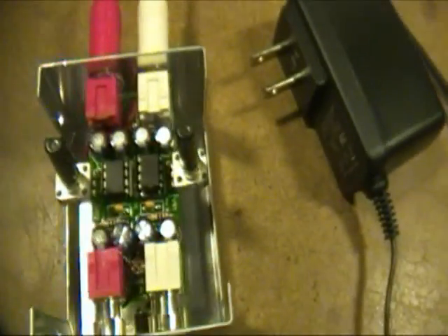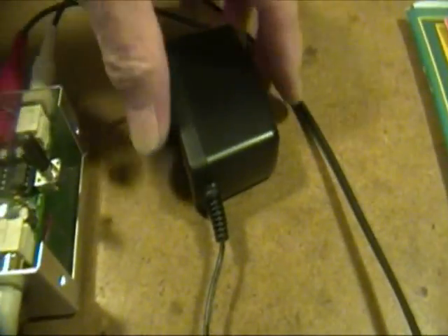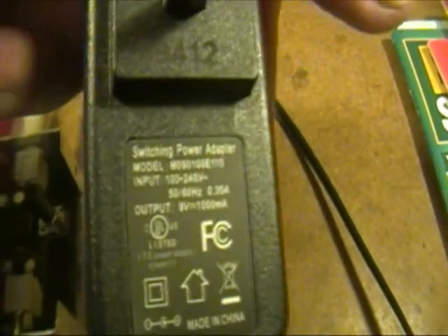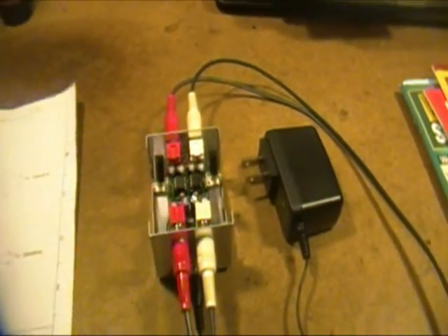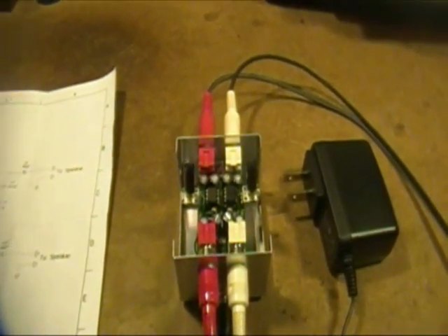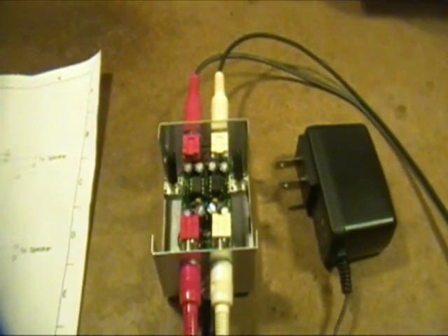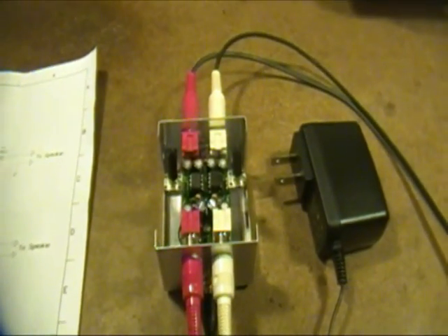I put it in a small aluminum utility box and added a power supply. This is one of those little switching mode power supplies that puts out, I think this is a 9-volt supply. This is 1,000 milliamps. You don't, of course, need that much current. But at any rate, this is an answer to the problem of low line levels. If you are trying to convert HDMI to composite, the audio will tend to come out, at least in my experience, a lot lower than it was on the HDMI signal. So this helps to boost it back up and you get it back to the normal level.